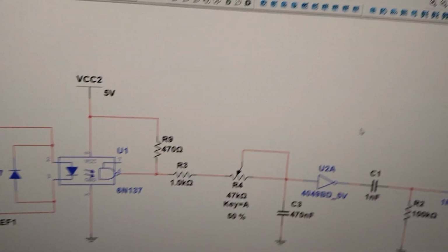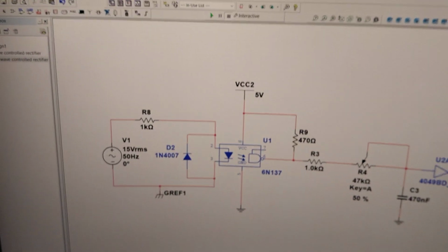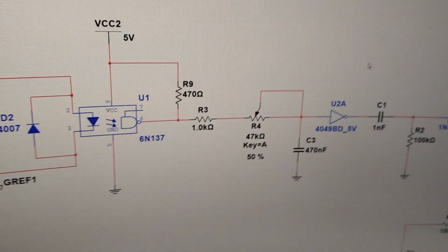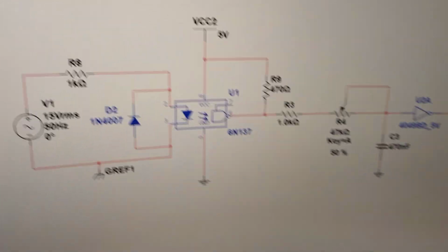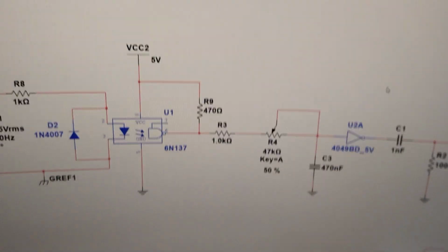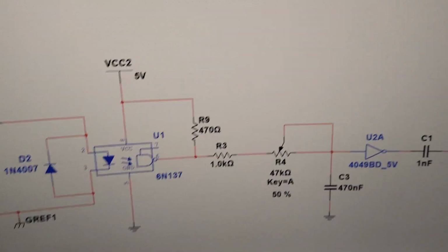So what we do here is, after that we get this, it's going to convert our sine basically into a sort of square wave output, you could say an inverted square wave. And square waves are easy to handle, you can just classify it as a high or low. Sine varies over time, and that's a little tougher to handle. So digital is good, we convert it, and this runs on 5 volts. It's a logic level optocoupler.